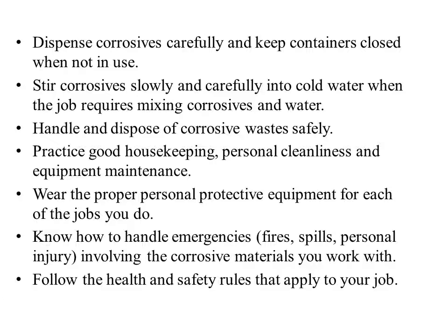We should practice good housekeeping, personal cleanliness, and equipment maintenance. When we say maintain cleanliness at all times in the workplace, it means we should clean up any spills and buildups of corrosives promptly and safely. We should properly dispose of unlabeled or contaminated chemicals. We should remove empty containers at once from work areas. And we should ensure that all containers for waste are properly marked and easily located.